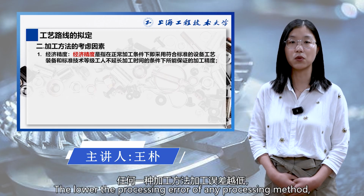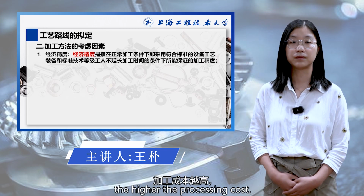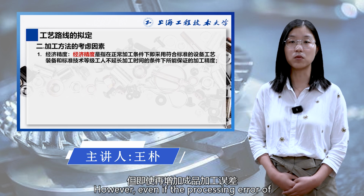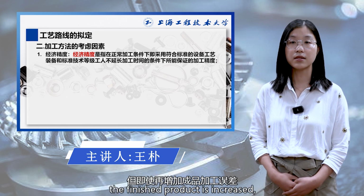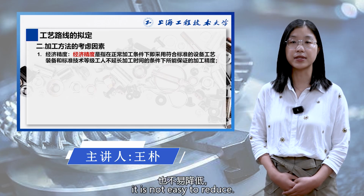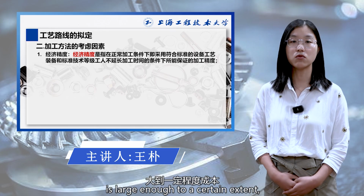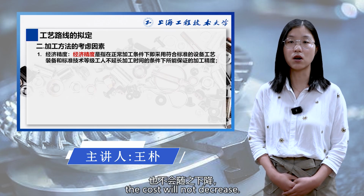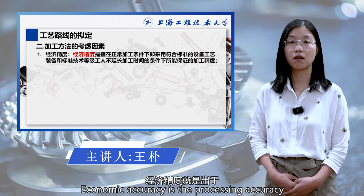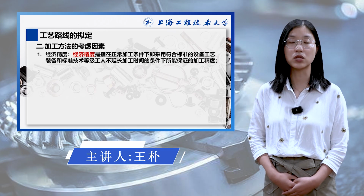The lower the processing error of any processing method, the higher the processing cost. However, even if the processing error of the finished product is increased, it is not easy to reduce. Conversely, when the processing error is large enough to a certain extent, the cost will not decrease. Economic accuracy is the processing accuracy between the above two situations.